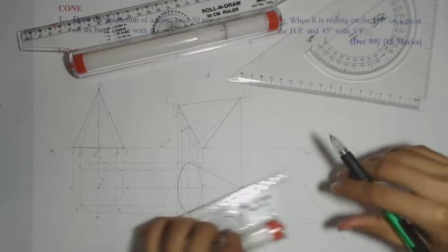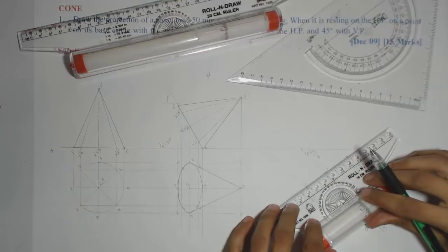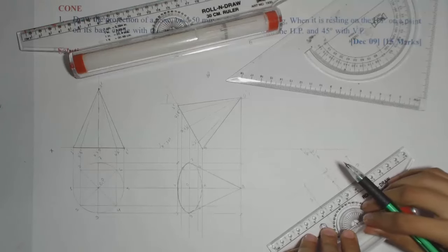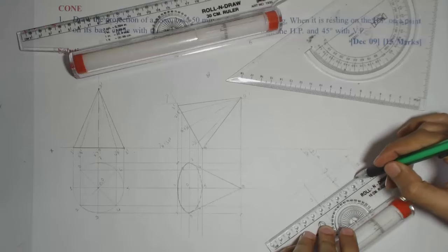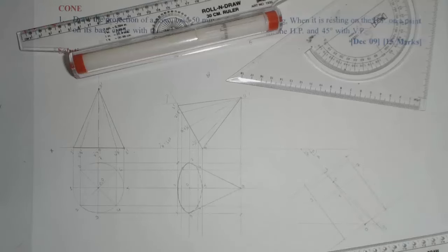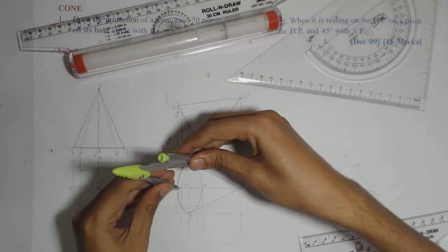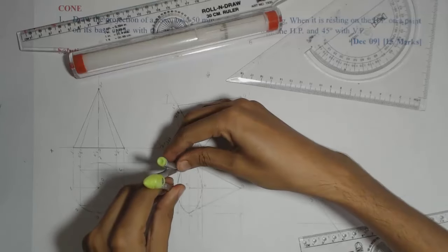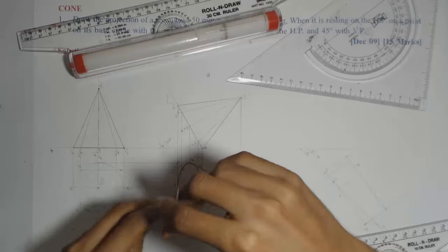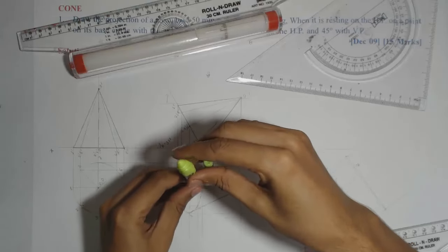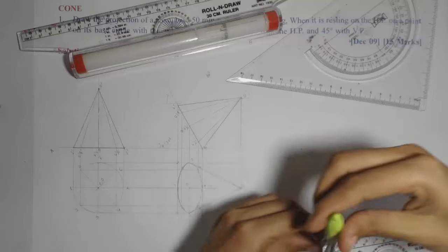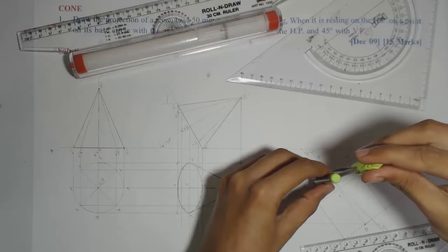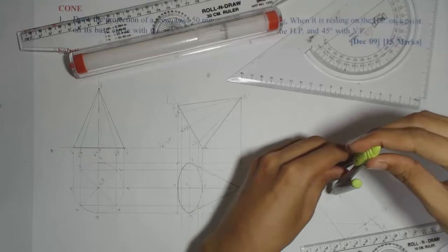Okay. So we will draw parallel lines. On this line only we are going to get 2 and 8, and on this line we are going to get 4 and 6. Now we can take only one distance and mark all 4 points, because if you see from the center line, the distance for 8 is same as distance for 2. Again, that distance can be taken for 6 and 4 also. So from the center line, I'll mark 4 arcs on the 2 parallel lines to get the remaining points on the ellipse.